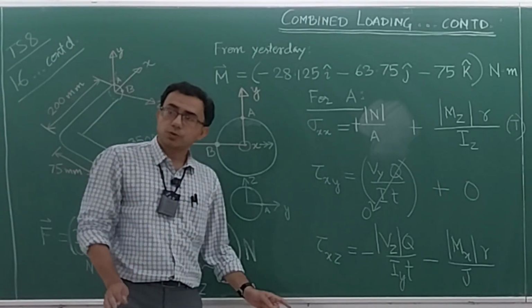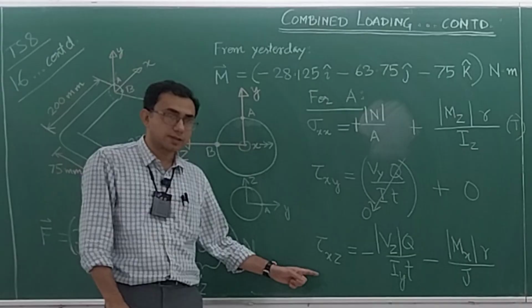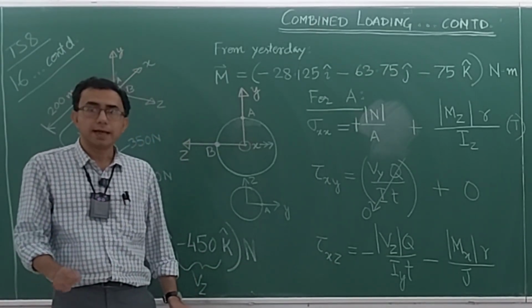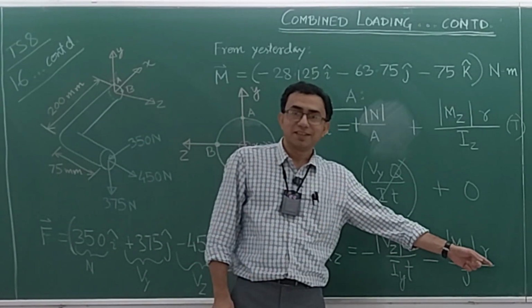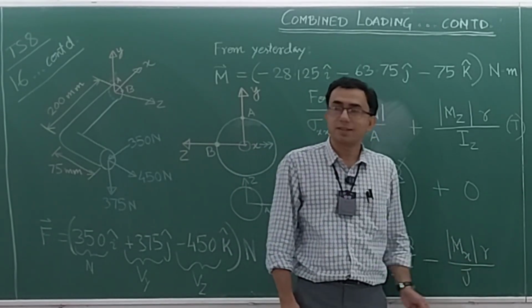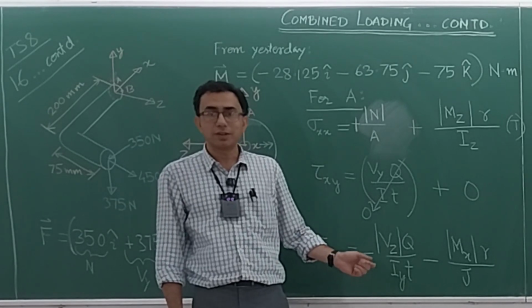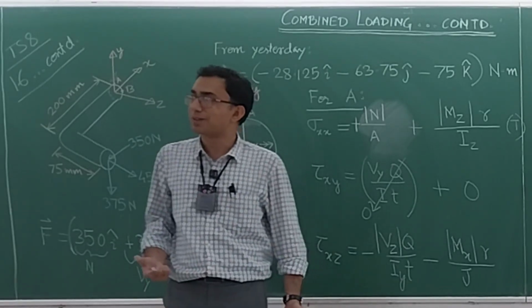But, and this also your seniors have done, they do everything correctly, shear stress, all the plus minus business, perfect answer to the third decimal place, and then finally they write C. C means compressive, because there is a minus sign, and I have taught them in class that there is a plus or minus, so it is tensile or compressive. But in shear stress, what is tensile and what is compressive?